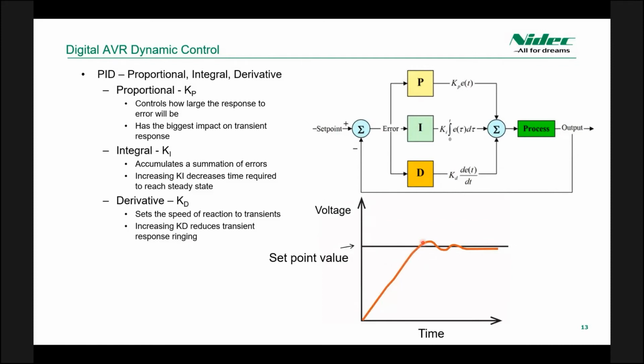And then when we start approaching the set point, that's where the derivative is going to kick in. It's going to see that we are getting closer and closer to the set point, and it will work to try to make sure that we don't way overshoot the set point. And a lot of times you're going to have a little bit of overshoot, but the derivative is there to mitigate as much as it can the overshoot when you're approaching the set point again. Then we have here some fluttering around the set point, and that's what the integral is going to try to take care of. It's going to see the fact that we're hitting a plus and a minus, and we're fluttering around the set point, and it will work to smooth out those bumps so we get a steady flatline output at the set point.